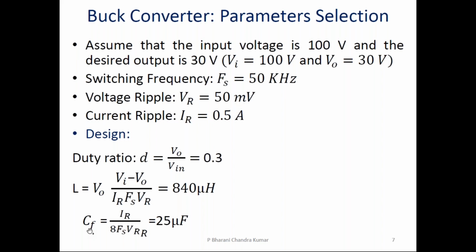So if you know that it is fixed, and always I need, let us assume, 5 volts itself, then you can go with the static control. This is the static control design, and I will show you how to implement this one as well. However, if you want dynamic desired outputs at various instants for your application, then this design will not work. For that, we have to go for the active control, which is the PID controller or LQR controller.